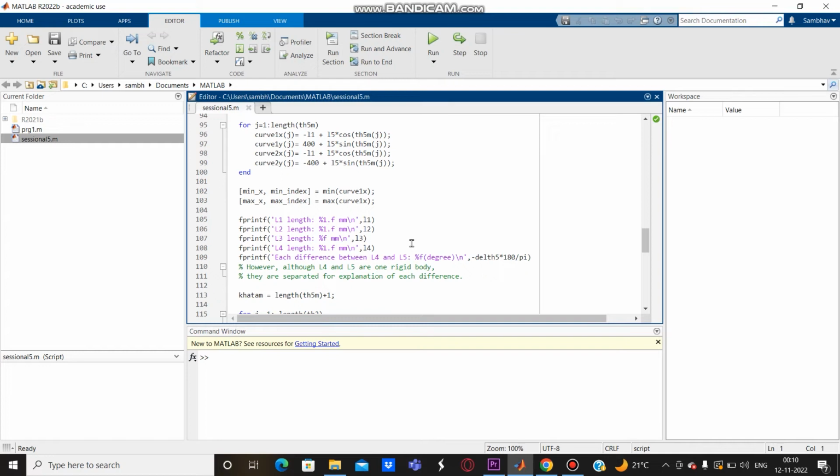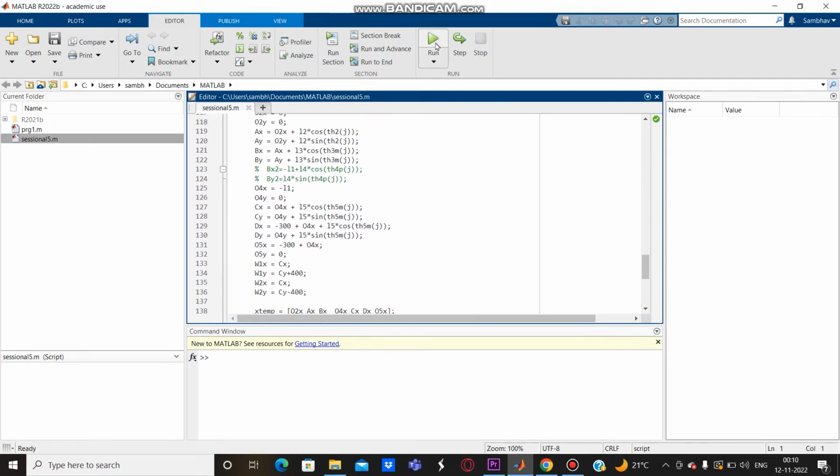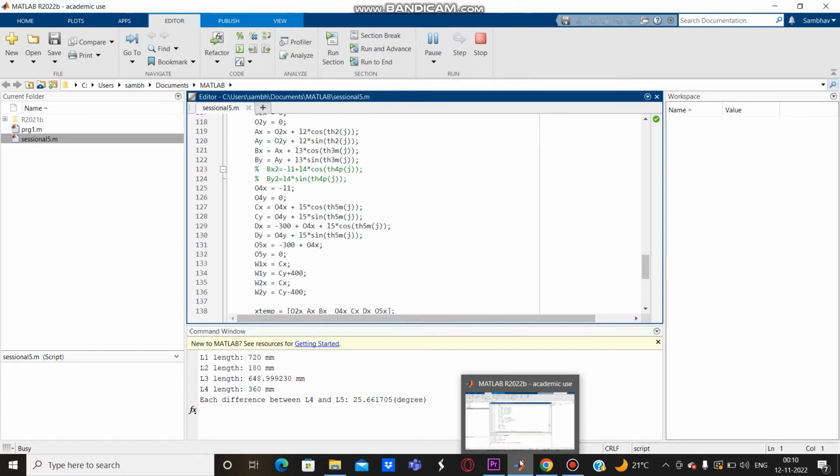After the mechanism is set, we rotate the crank, and as its coordinates change, the effects are seen on the coordinates of the other links, and thus the entire windshield wiper mechanism moves. But our focus here is the motion of the ultimate wiper which carries out the wiping action. So now let's run the simulation and have a look at the results.